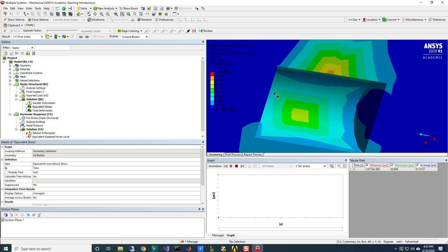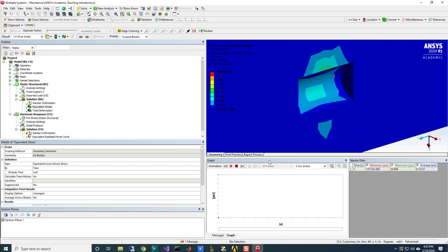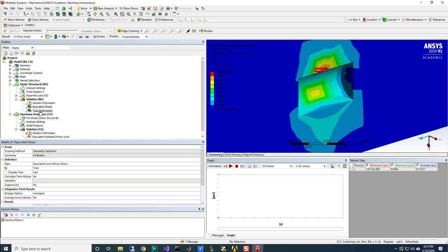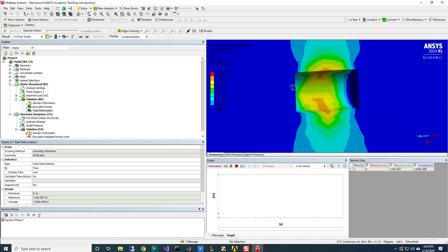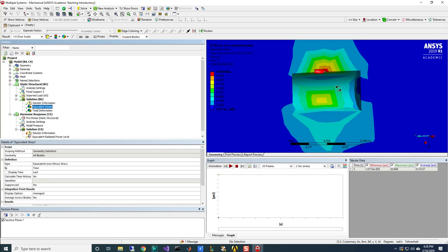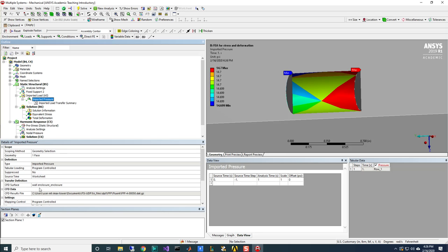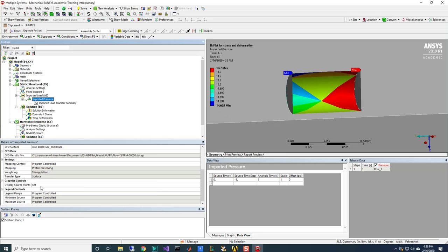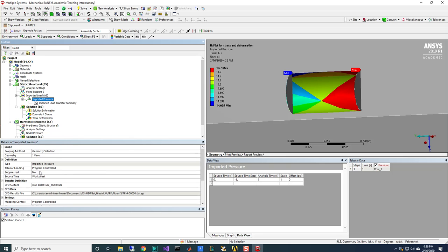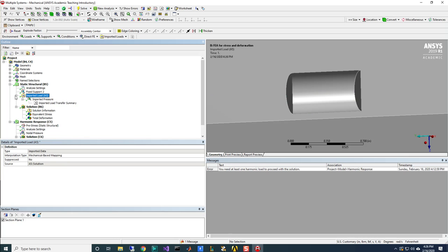The way that we're going to do this is we're going to do an initial steady state flow calculation as an initial condition, and then we'll plug that into a transient analysis. So let's open up CFX. Our working fluid is going to be water. We do not need to solve any heat transfer equations, so I will disable them. I'll leave the analysis type steady state for now.